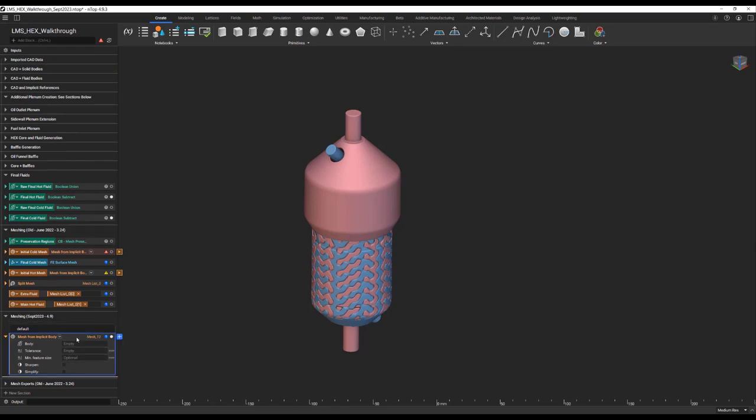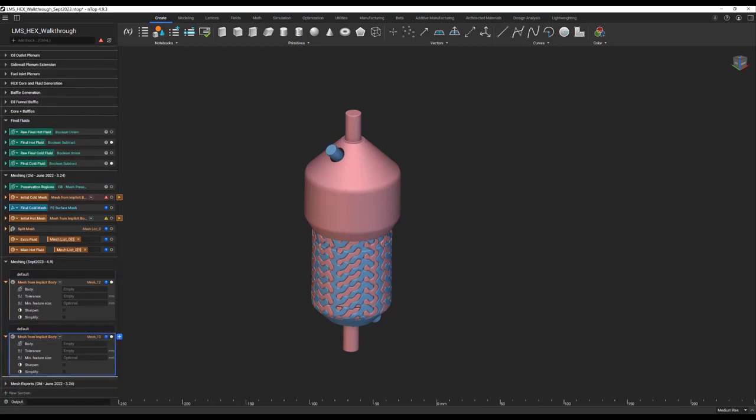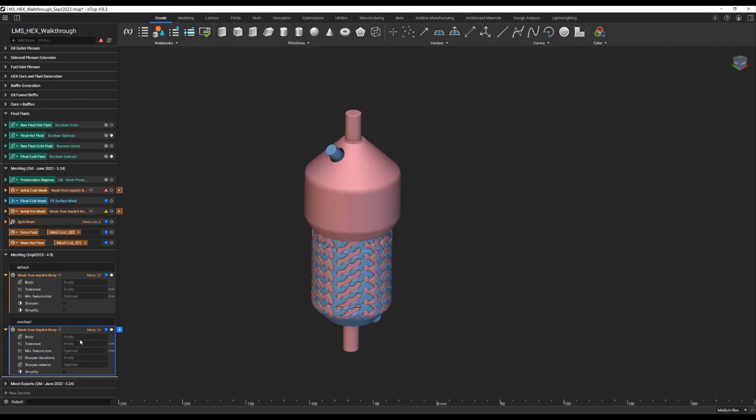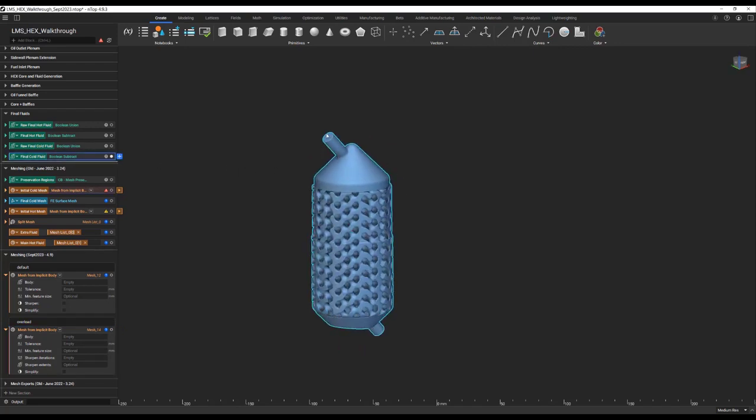If I Control C, Control V the block, it'll copy and paste a new one, and I'm going to relabel this comment to overload. I can click the down arrow and access the overload option, and all this is going to do is expose a handful of new inputs. Virtually any time I use this block, especially if I want to select edges to preserve their sharpness on, I'll access the overload. The main reason being, and I'll show you a time comparison between the two, is in most cases, at least let's talk about the CFD, we really only care about preserving the edges, in this case at the inlet and outlet boundaries.